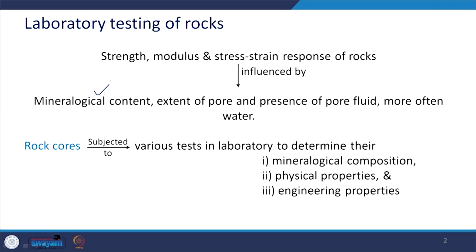Basically, the strength, modulus and stress strain response of the rocks are significantly influenced by the mineralogical content of that rock, the extent of pore and the presence of pore fluid in them, which is quite often water.